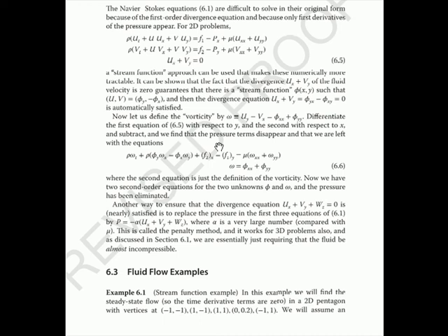On the free-flow boundary, what have we got? Well, remember, v is 0, and let's just look at the bottom. This is going to work on other boundaries too, but on the bottom, remember, v is 0, and u sub y is 0. So if v is 0, that means phi sub x is 0, which means phi is constant along the boundary, and we can just take it to be 0. So we have phi equals 0 again there.